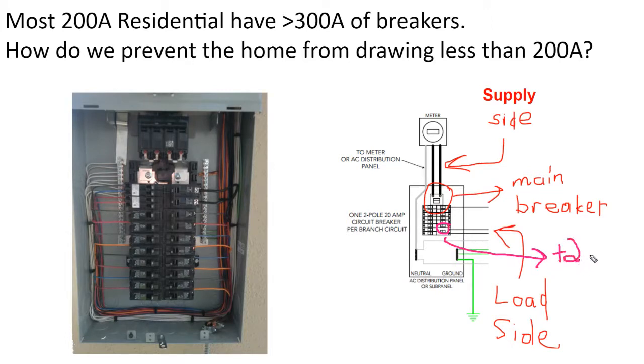In other words, a 200 amp electric service panel can be fed with 240 amps of power divided between the utility main breaker and the solar array.